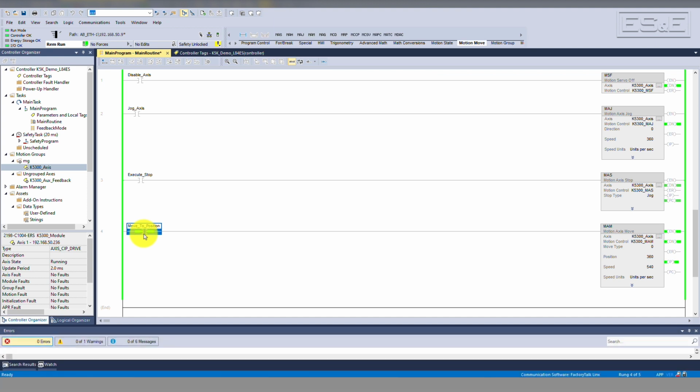As you can see, when the rung is true, the enable bit is true. This instruction executed successfully, so you can see that the done bit is also true. You can also see that the in process bit turned on and then back off when the instruction finished. When the instruction finished, the PC bit turned on.